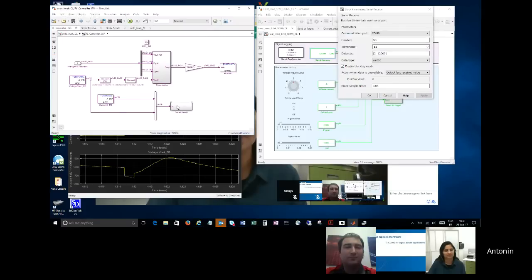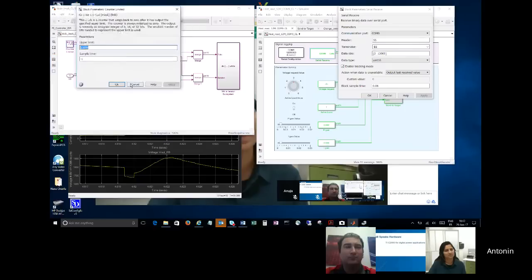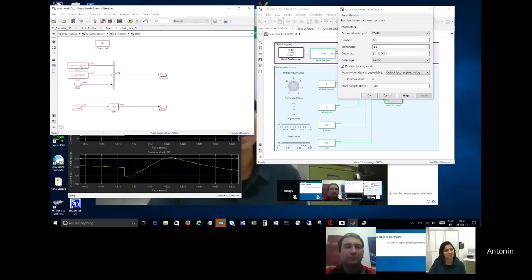And inside this serial send, it's a little complicated, but you'll realize that actually what it does is pretty simple. I have a counter that counts up to 12,000, and every 12,000, I'm going to go ahead and add a few ASCII characters, 4545 and 5353. These are the SS and the EE you see here. So basically, I'm sending data, and every 12,000, I'm just inserting the start sequence and the end sequence. So I'm actually inserting the end sequence for the previous data and the start sequence for the new data. So that will help Simulink get synchronized with the data I'm receiving.